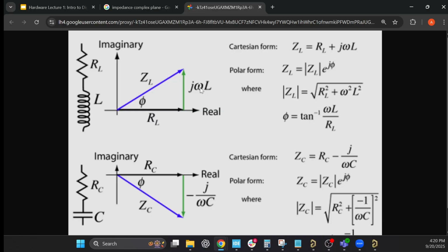Omega is the frequency, which comes down to the fact that you have frequency-dependent effects, times the inductance. And then this gives you your Z value, which you can either state as the absolute value of it, and just talk about how much impedance it is. But more correctly, you state how much of it is resistive, how much of it is inductive. In the exact same way, with a capacitive system, you have some resistance and the capacitance, with a slightly different formula like this.